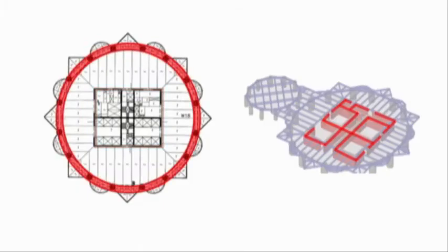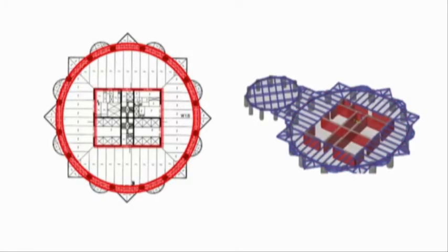The central structure of Petronas Twin Tower is based on a core, 23 by 23 meters, basically concrete, attached to a per-pier ring of 16 concrete columns. This inner core system has strength to resist 50% overturning moment which is caused by lateral force.